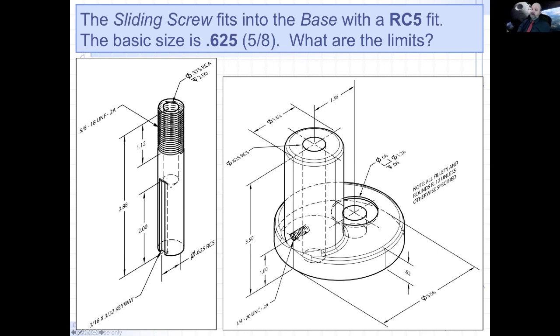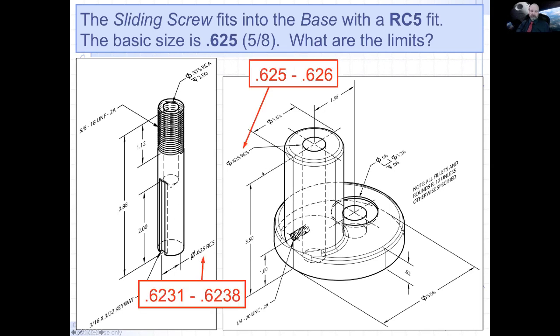So now you look it up. If you're machining this for someone, you look it up and say, what range can I have on this shaft, right? And what range can I have for this hole? So once you look it up, you can say, oh, okay, this is what my allowable range is. You can see, since it's a 5, it's pretty tight, right? And the hole is the same way. It's kind of tight as well. Okay, so that's a very tight tolerancing. All right.